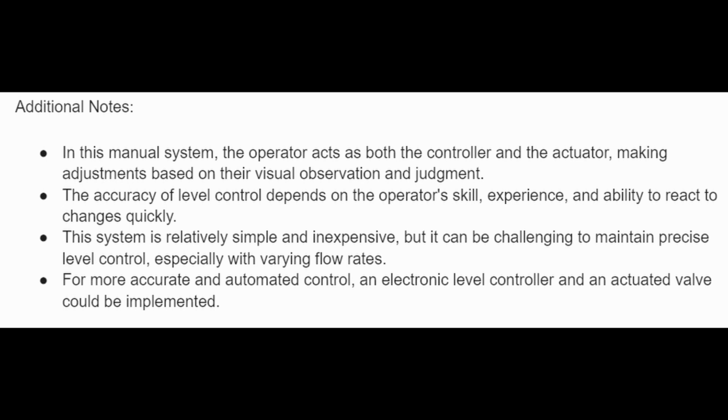The accuracy of level control depends on the operator's skill, experience, and ability to react to changes quickly. This system is relatively simple and inexpensive, but it can be challenging to maintain precise level control, especially with varying flow rates. For more accurate and automated control, an electronic level controller and an actuated valve could be implemented.